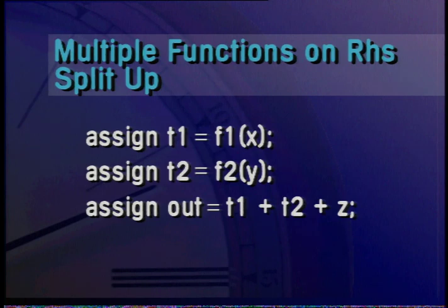To avoid this reevaluation, you must use intermediate assignments like so. Writing the assignment this way in essence tells the Verilog compiler that there are no undeclared dependencies between f1 and f2. Another example which is similar in spirit to this is the cascaded ?